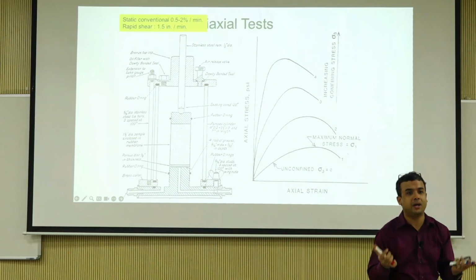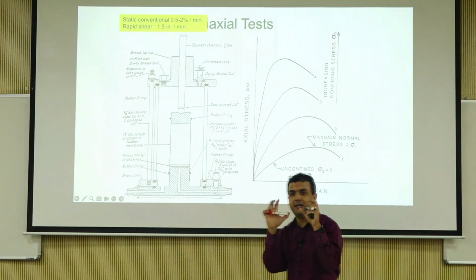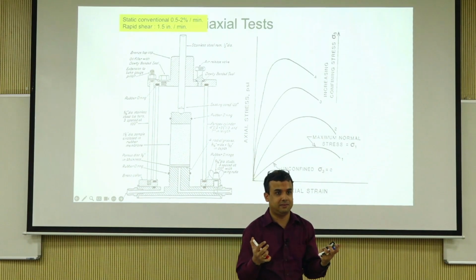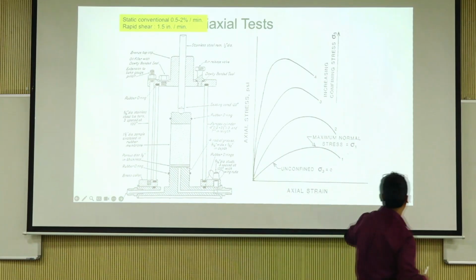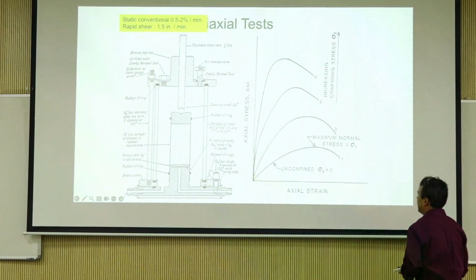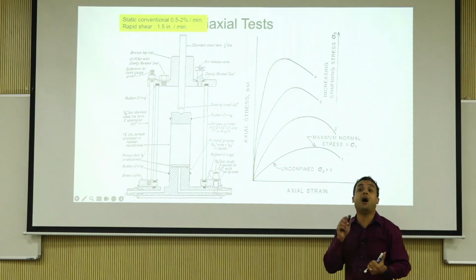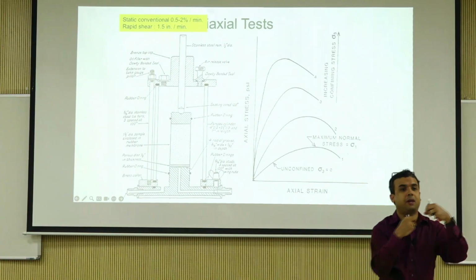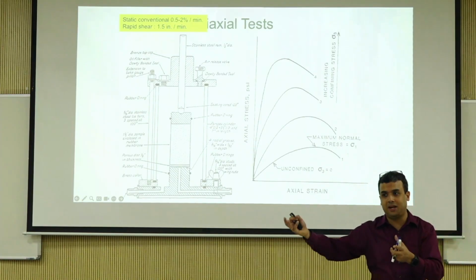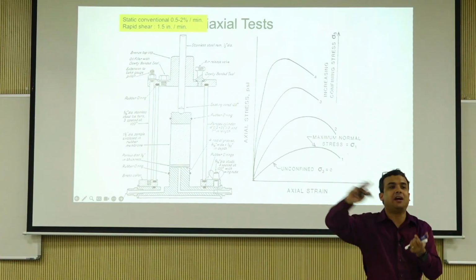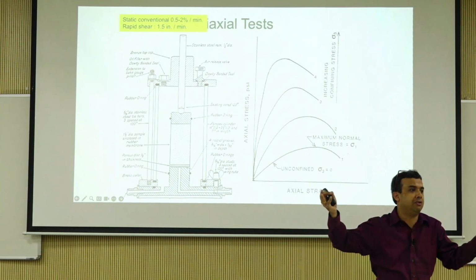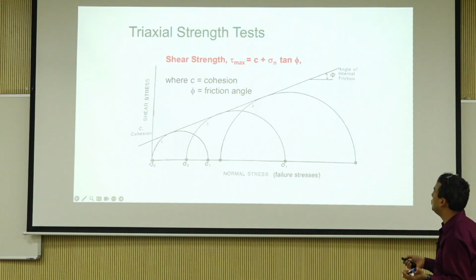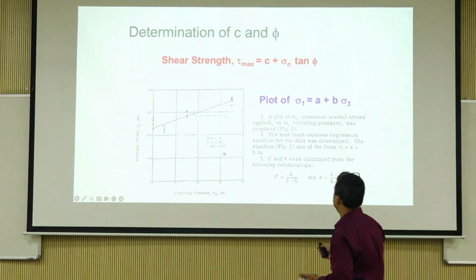Once it is held together, because the particles don't crush, you actually have an immense amount of strength, right? So that is the reason confining will increase your shear strength a lot of times, as long as it is being translated into interparticle contact. If it is saturated, if it is an undrained condition, if water is taking all the load, soil does not care, right? That's what happens. You saw this. We're going to do this in the tutorial today.